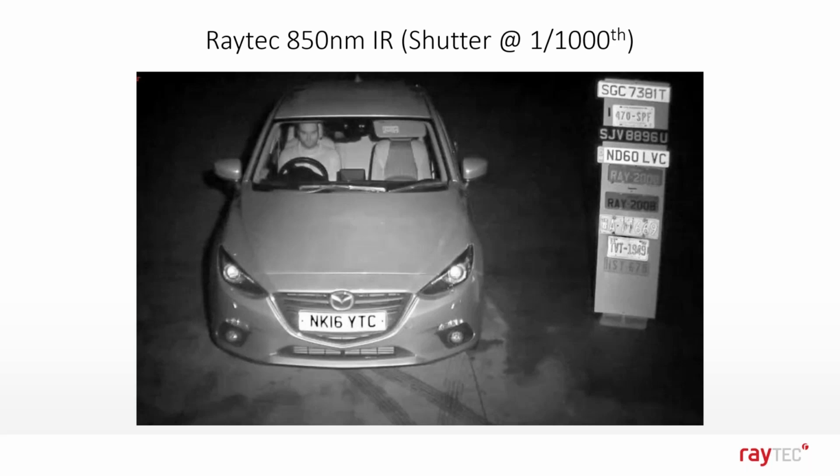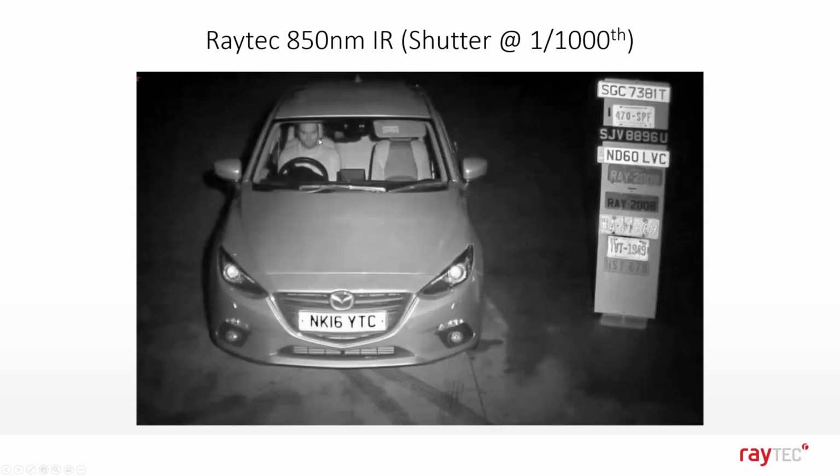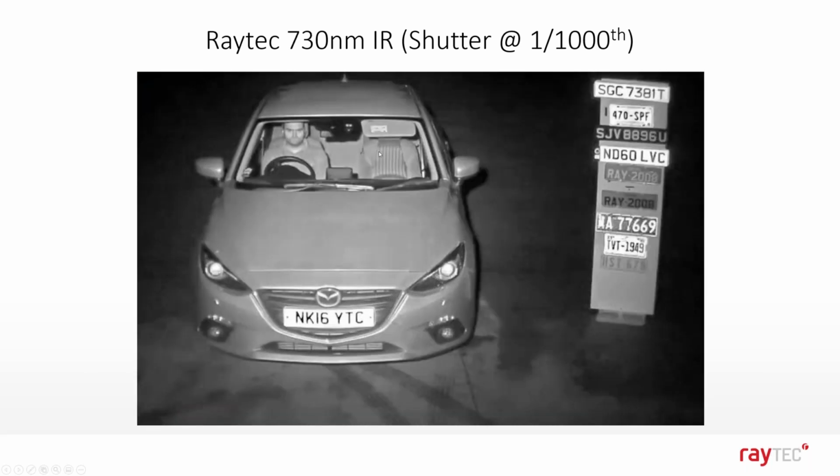But if we change that to 730, you can see the difference. So 730 nanometers, a little bit more visible when you look directly at it, but it's a much better wavelength at penetrating the windscreen. So you can see, I'll just go back a slide. It's a lot more blurry there. So yes, the car, everything like that looks absolutely fine. But as you go through the windscreen, we're probably not going to recognize that person, and you can see things even like the pattern of the seat. We're seeing a lot better with this wavelength as well.